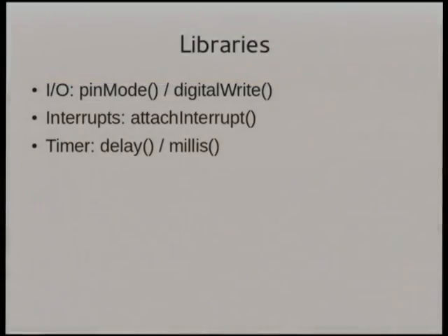Because you're not using a bootloader though, that means that you don't have to have the automatic reset if you're doing it all by hand. So the libraries, what comes in the libraries that's useful?